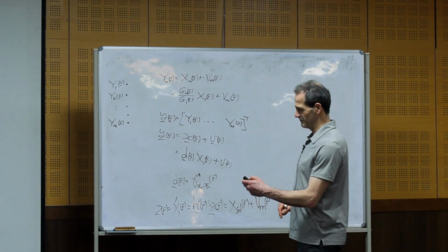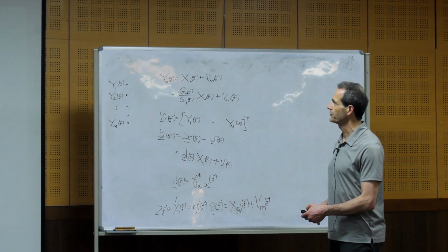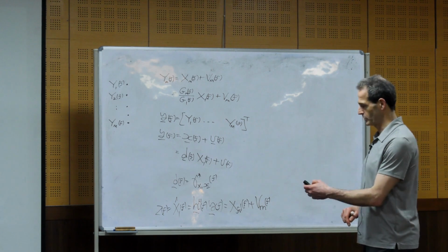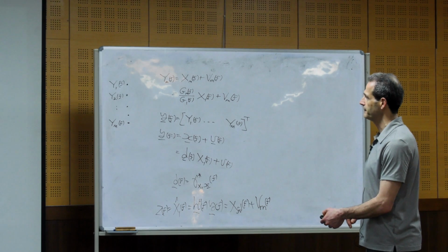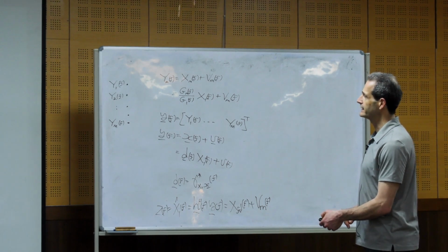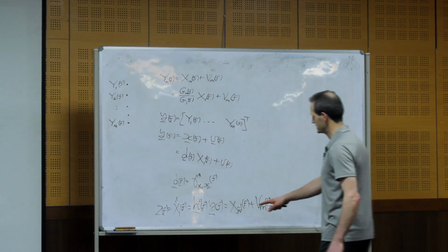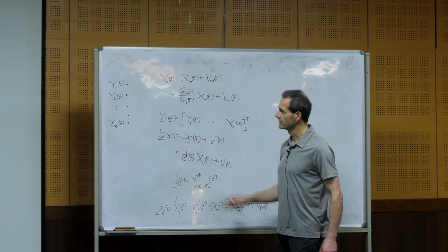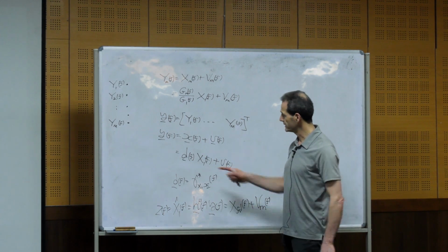Okay, so the desired signal reduction factor, and then we also have the distortion index, the desired signal distortion index, narrowband and broadband, which means what is the mean squared error between X filter desired and X1, normalized by the variance of X1.